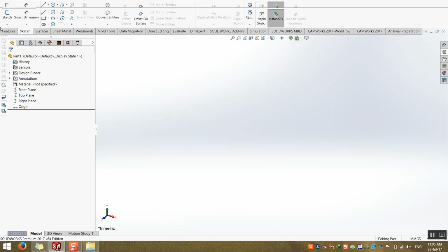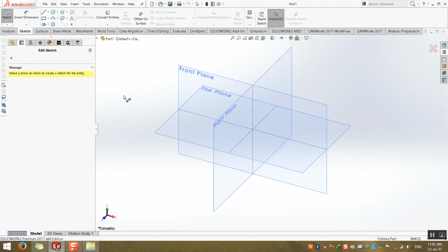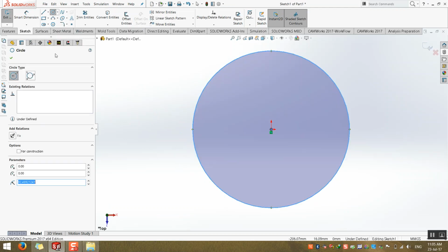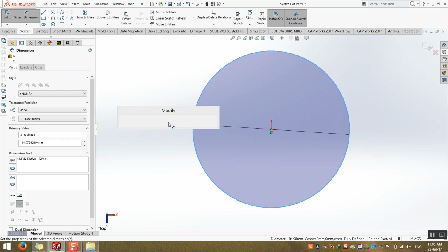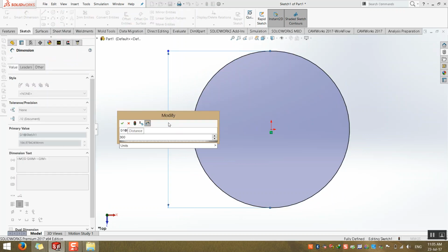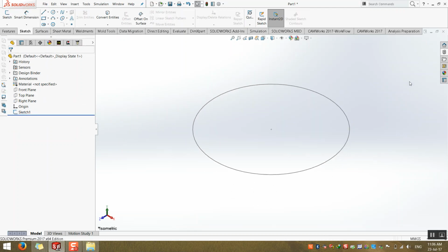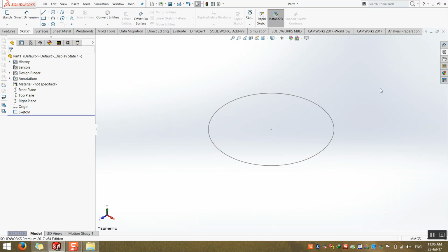This means the first thing you should know, in Solidworks or any software, is to go to sketch and top plane and draw a circle. 3 meter diameter, the external. 3 meters or 3000 millimeters. This circle will be the base of your spiral.